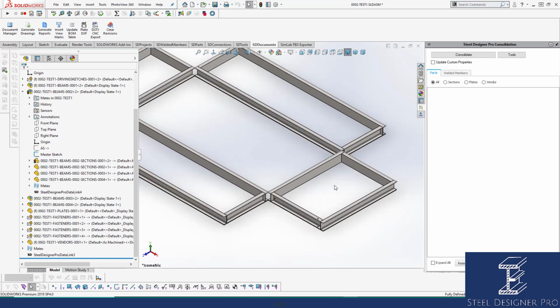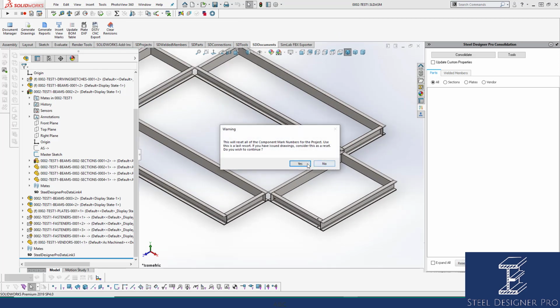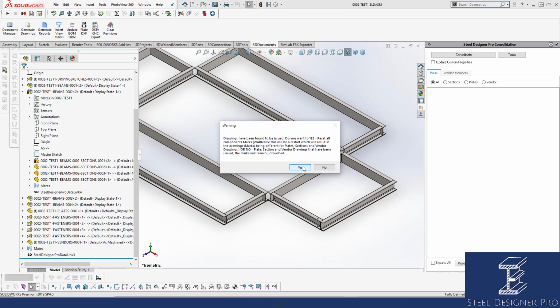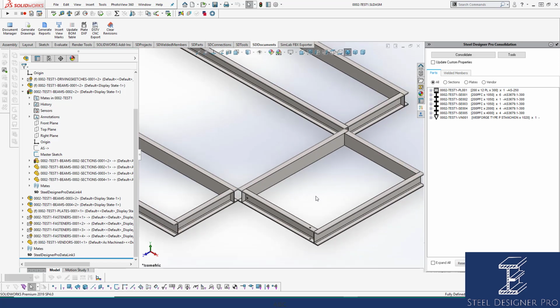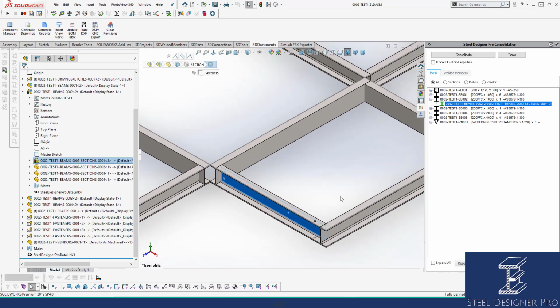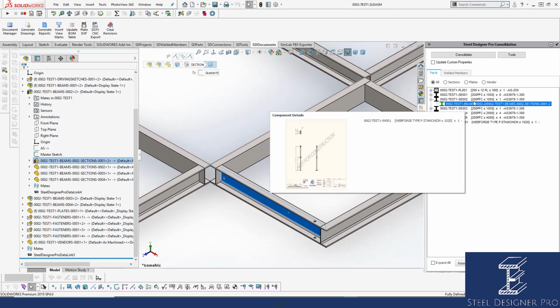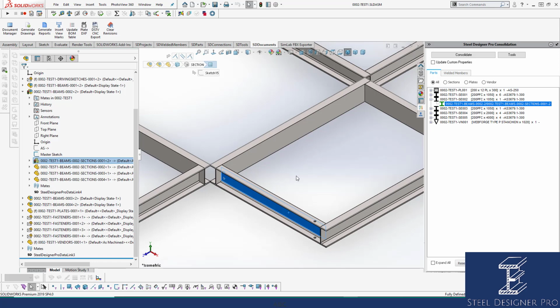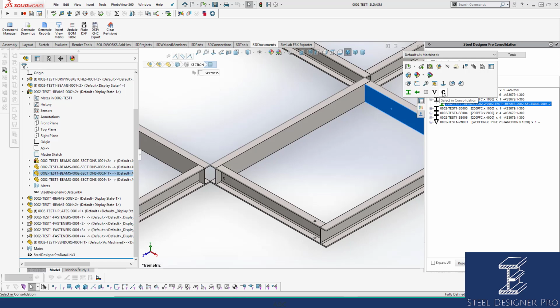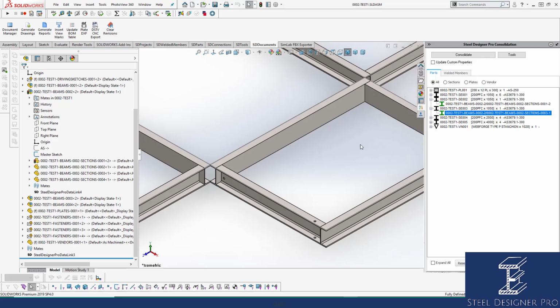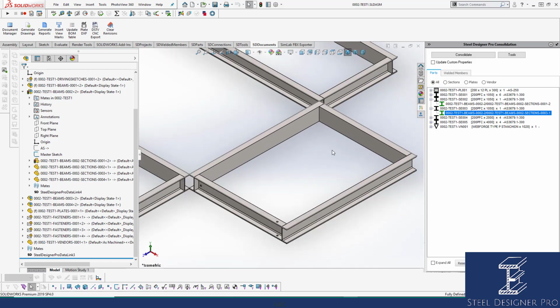But now that I've made changes to that, I'm going to reset my marks. So I clean it up, and there have been drawings issued, so it's only going to reset a component mark. And if we look at this, it now has the mark of being section 2. It must have been the parent mark. The other mark has now moved over because this was one of them, so that's now separate. So now it's become section 3. So consolidation picks that up.